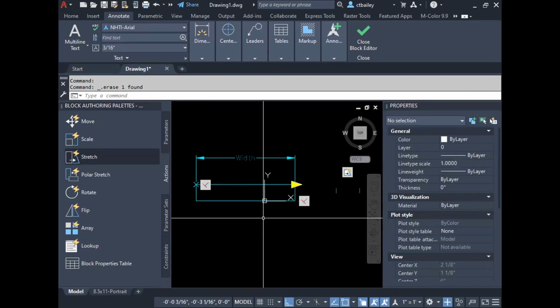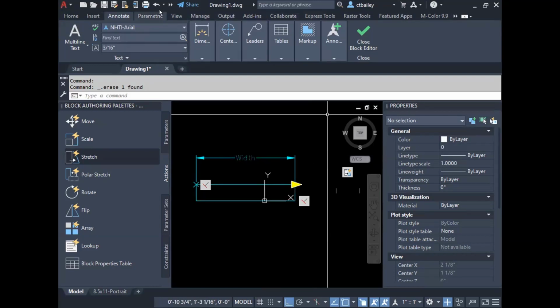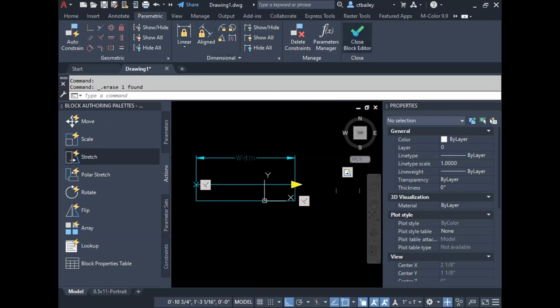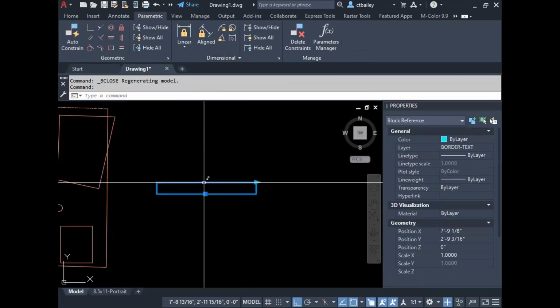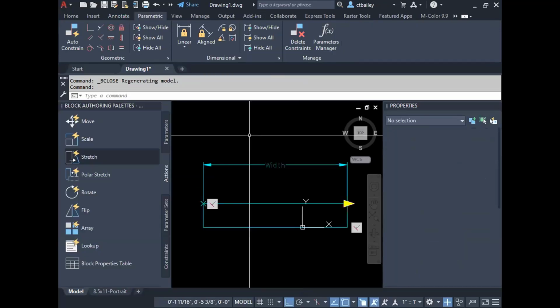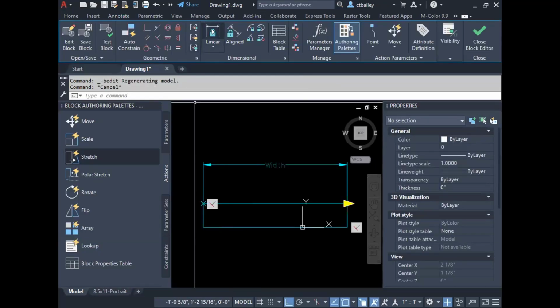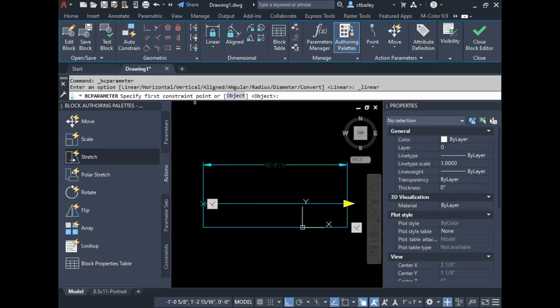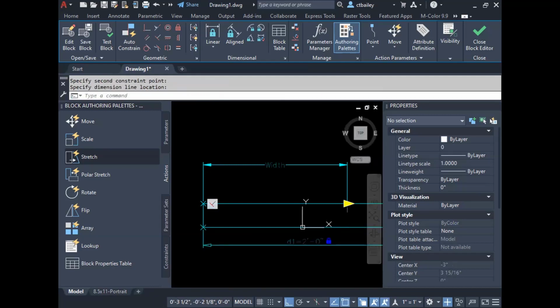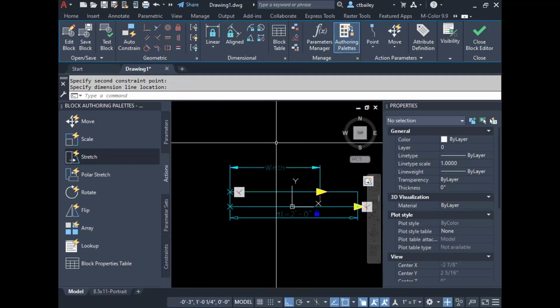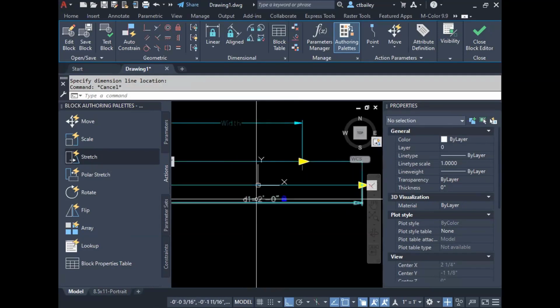And so I wanted to quickly set it to the distance that I wanted it to be. So I cheated a little bit. I used a parametric. Oh, I've got to be in the block editor. Sorry. I've got to go back in. Hold on. Something weird happened there. I want to add a linear parameter to the bottom part. And I'm going to set it to 24 inches, just 24, enter. It pushes it out to exactly what I wanted, okay? I'm in charge because I'm the guy who's in charge of it. I'm the boss of it. So I've got it out to 2 foot.